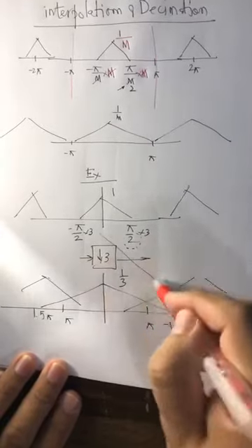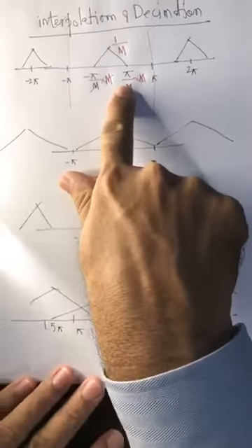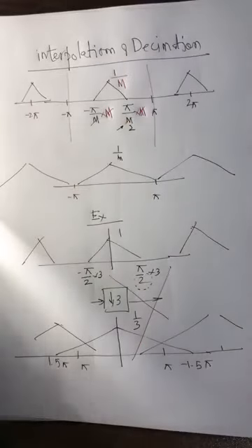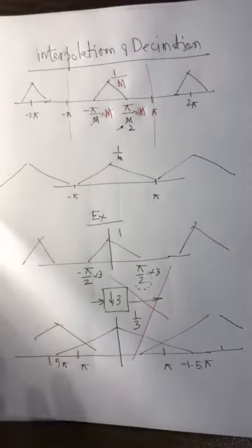So this you must never do. You got to be very cautious once you are decimating a signal, that you need to make sure that you are not disobeying Nyquist in any sense. So Nyquist has to be obeyed, and obeying Nyquist means that you got to be very particular about the value. You got to plot your spectrum. So take FFT, the amplitude of the spectrum, and see the extent of your spectrum from minus pi to pi, and then decide at what rate you should decimate.